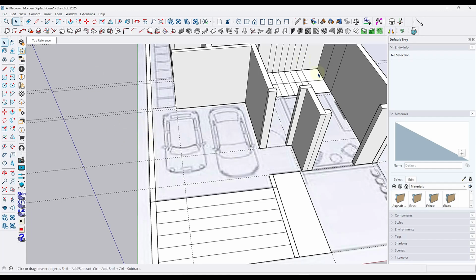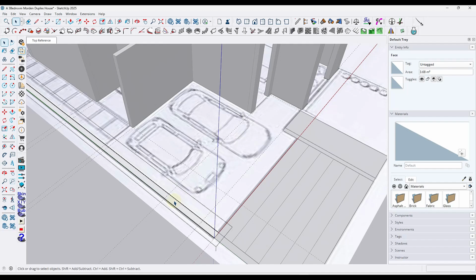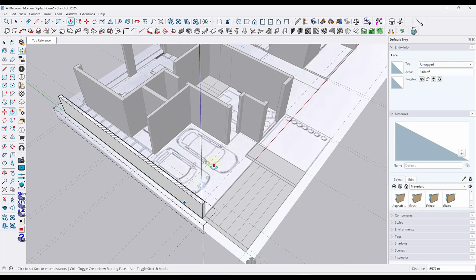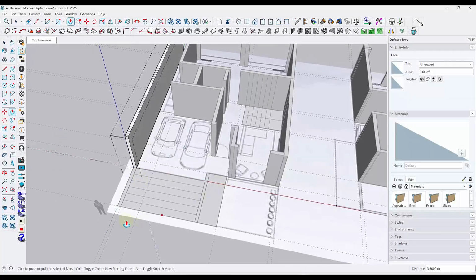This is the navigation space where we are drawing, so we can double click on this area here. If you select this, you find out that you can now press P on your keyboard or left click on this blue bounding box, which shows us push pull. The push pull tool is used to extrude faces and create 3D forms, just like you see here. So we can click that or press P, and drag this up to this area. Okay, which is nice.